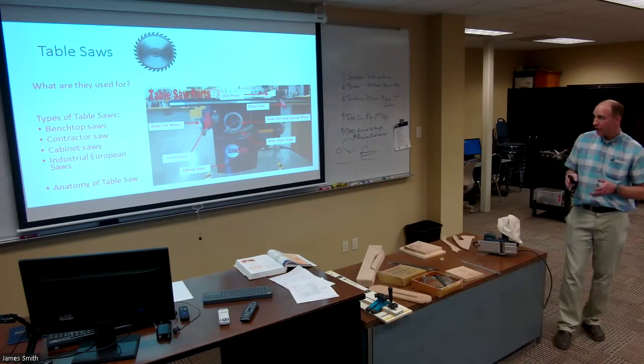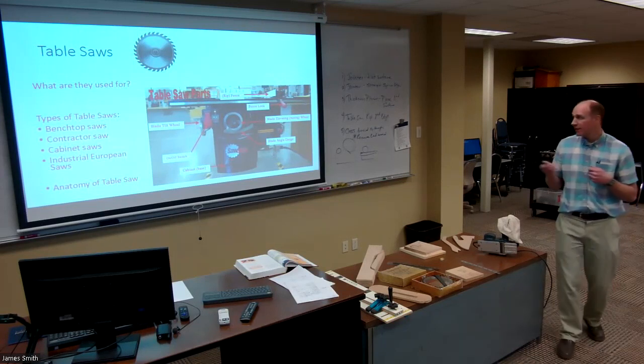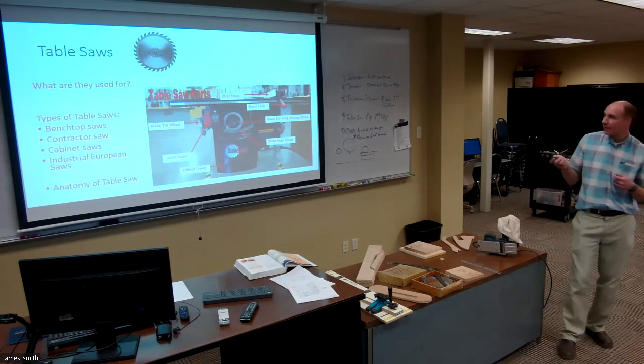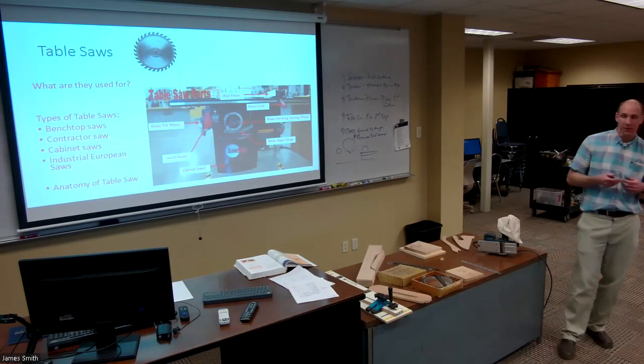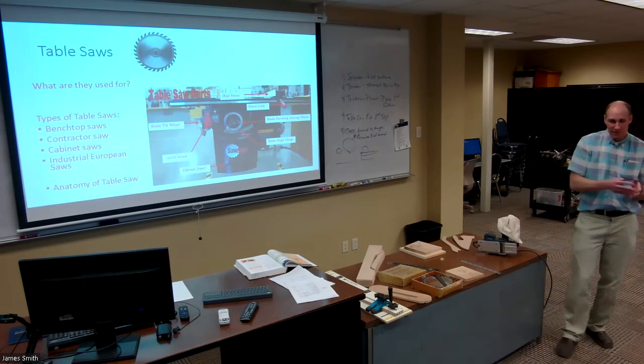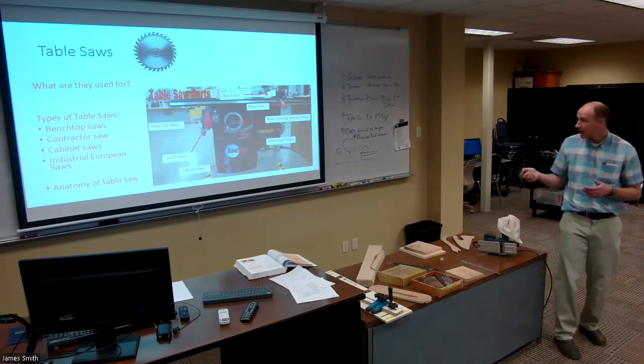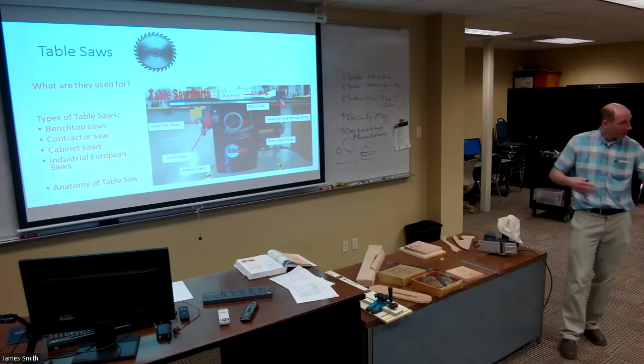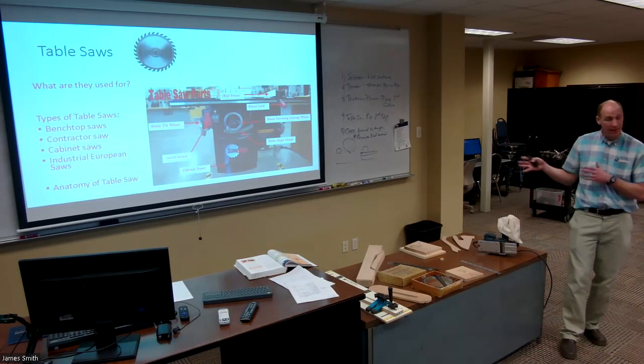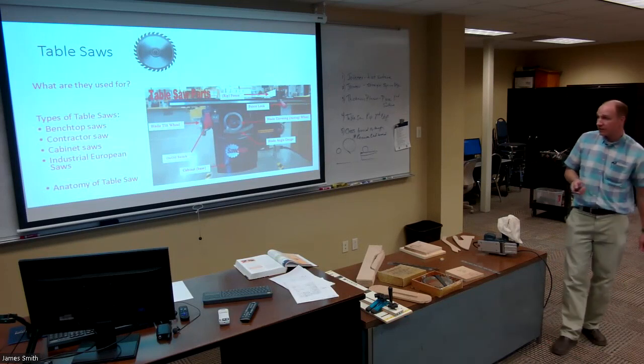It slides back and forth nicely, it's very accurate, and you have a nice material, like a Formica or melamine, on the ripping fence. They're designed for ripping plywood, and oftentimes you can cut 48 inches wide off to the right side of the blade. So those are really nice saws.